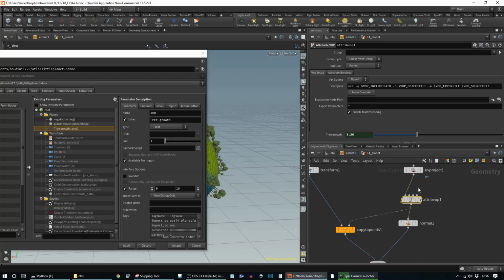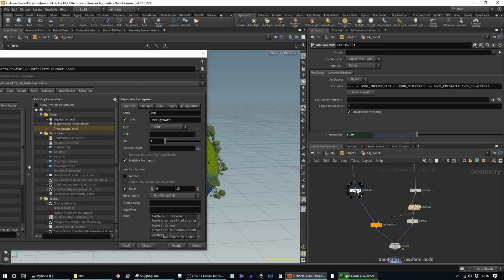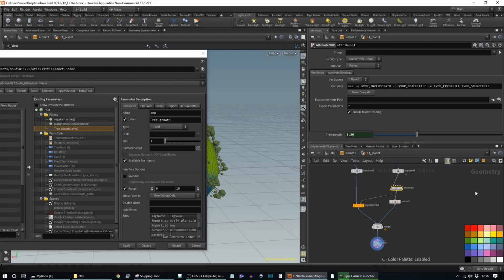You might want to go in and add some new attributes. I find that there are two ways of setting up networks that I know will become Houdini Digital Assets that can make this stage a bit easier. One is any nodes that have a parameter on them that I know that I'm going to want to access from the outside, I make a specific colour, usually bright yellow for some reason. So you can quickly at a glance see which nodes need to have parameters changed.